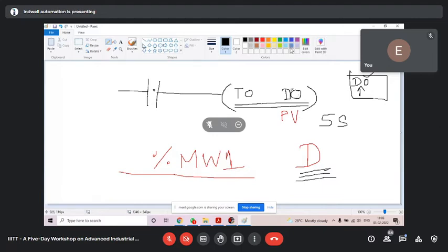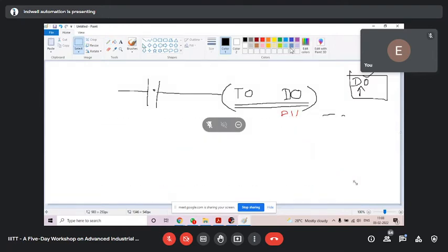For a different brand, like Allen Bradley, it is N7. Siemens has a similar address as we have in Codesys, like there you have MW1 or VW1. We have many variables in Siemens. So in different brands, you will have different variable addresses. For Mitsubishi, I told it will be D. So I have taken D0. For each timer, we will have to change the preset location. We will have to give D0, D1, D2, D3 like that. Is it clear? Yes, sir.